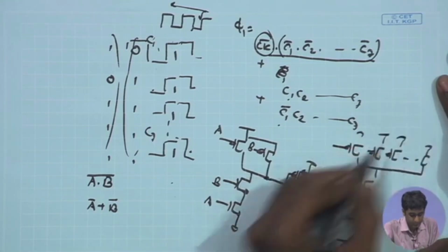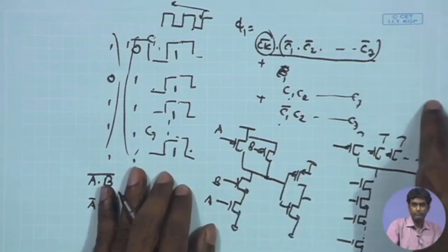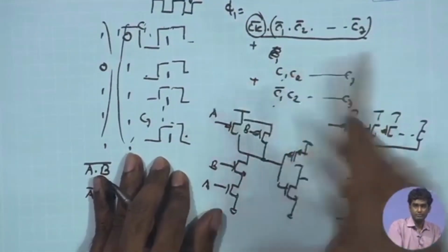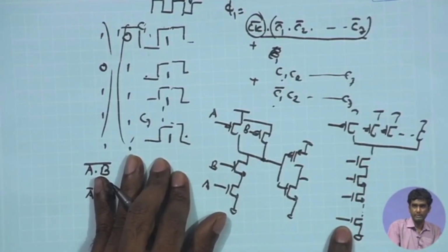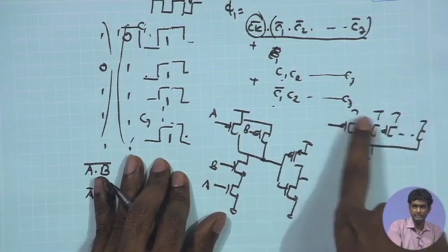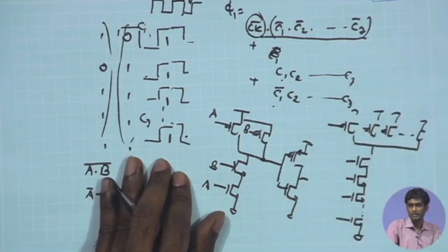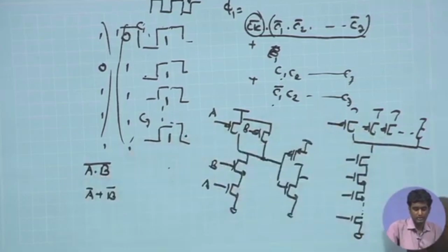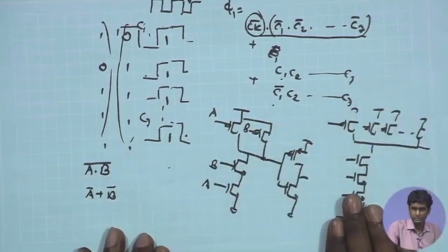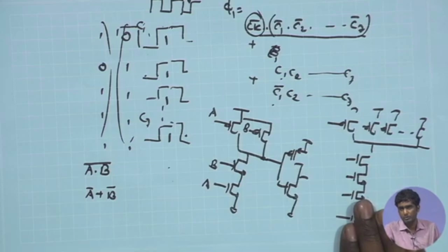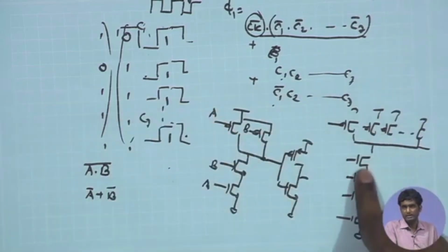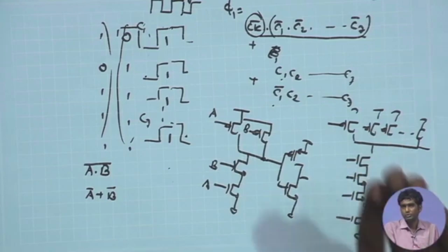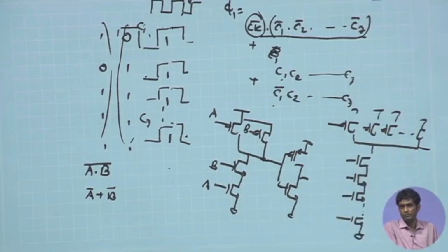So, if I want to implement the AND of all these functions together, I will have to use such a stack, the C1, C2, C3, C4, C7 coming till this point, and also the corresponding C1, C2, C3, C4 coming here. Ideally, of course, I can do this, and in digital circuits we do not need to worry about the voltage headroom just like we do in analog circuitry. These are just triode region switches, and ultimately the voltage drop across them can reach 0. So, I do not worry so much about the voltage headroom across the switches in digital operation,